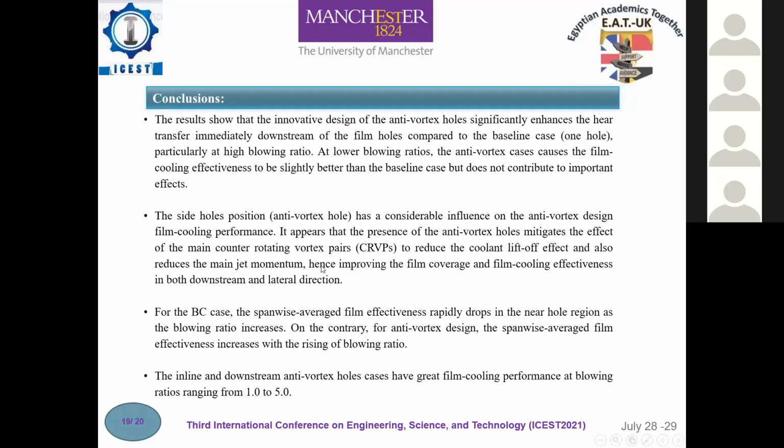The main conclusions of the present study are that the results show that the innovative design of the anti-vortex holes significantly enhances the heat transfer immediately downstream of the film holes compared to the baseline case, the standard one, especially at high blowing ratio. The side holes position, upstream, in-line, and downstream cases have a significant influence on the anti-vortex design film cooling performance. For the base case, the span-wise average film cooling effectiveness rapidly drops in the near hole region as the blowing ratio increases.